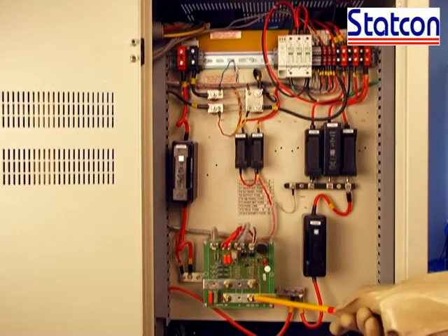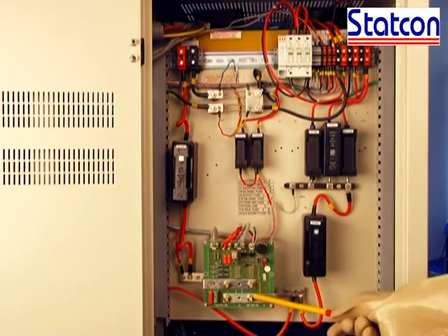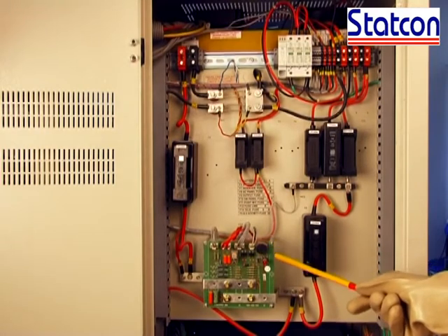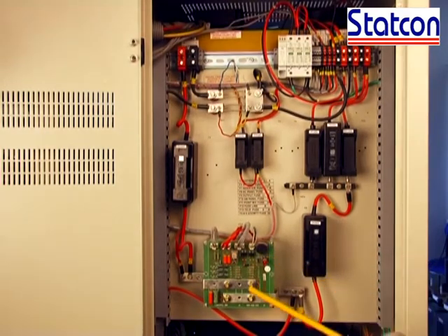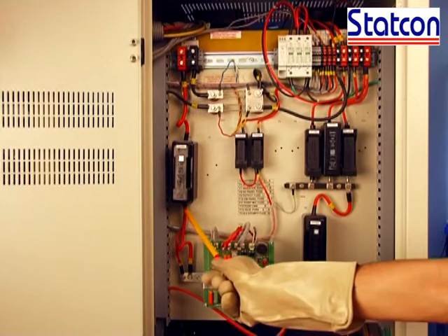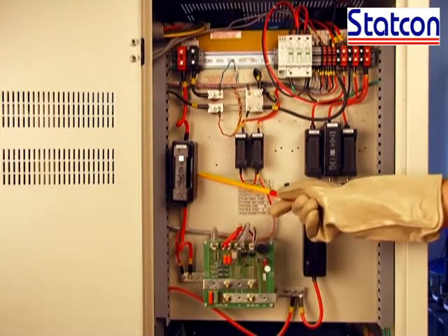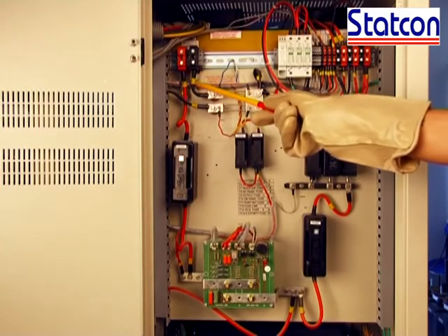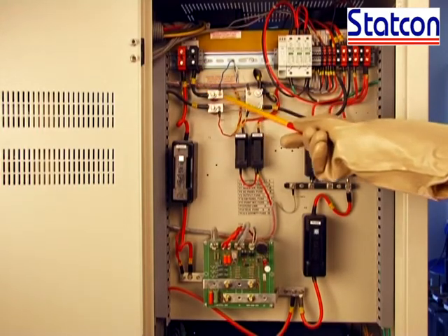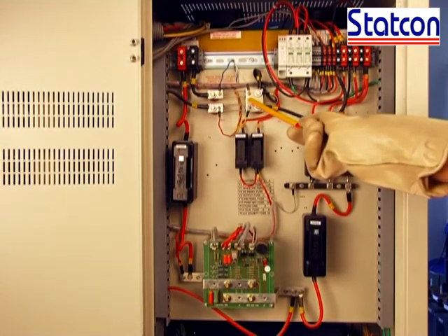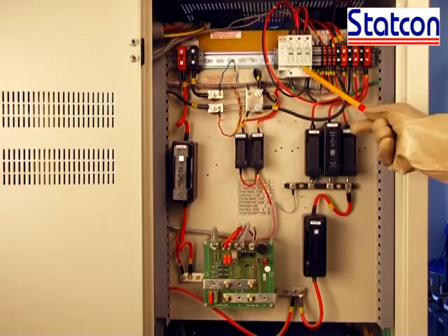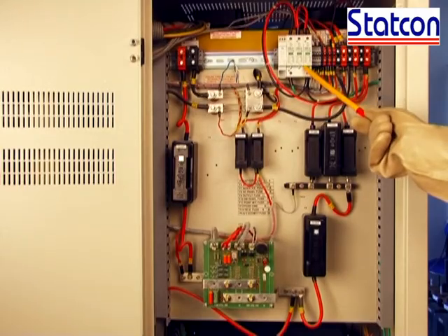This card provides protection from reverse polarity of battery terminals. In case of reverse connection, a red indication glows and the buzzer sounds. This card takes 110 volt DC supply from SMR and provides it to battery terminals. A battery fuse is also given between this card and battery terminal. Negative wire from SMR output is directly provided to the shunt. An SPD, surge protection device, is also provided with point machine terminal.